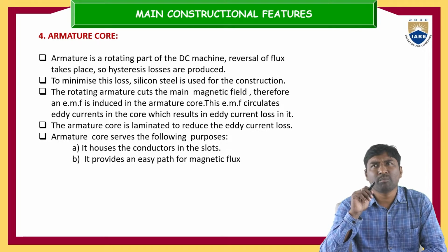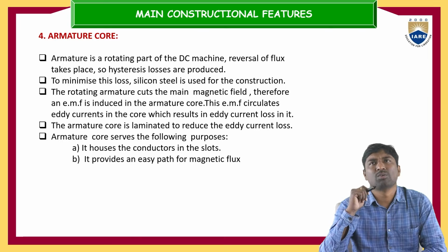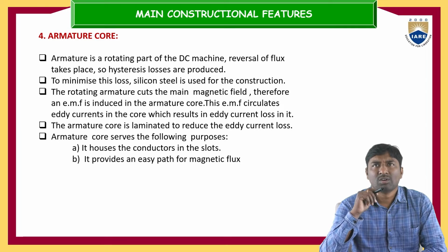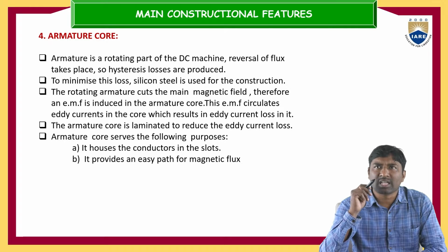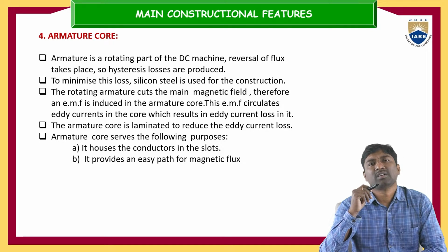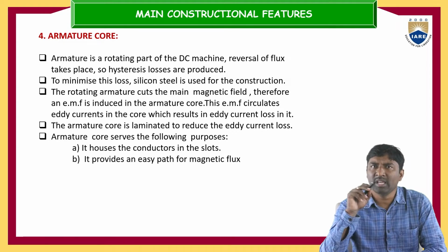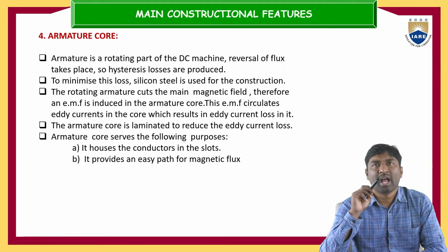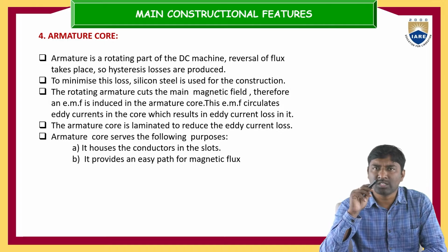This induced EMF circulates eddy currents in the core, which results in eddy current loss. So the armature core is laminated to reduce the eddy current losses.